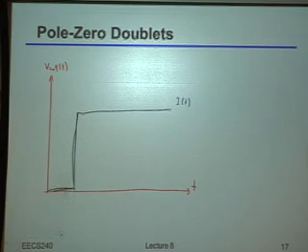Okay, well, if I have just some generic second-order system, then what you'll always get in terms of the output response, at least as long as it's overdamped, is something that looks like the composition of exponentials, where the time constants of each of the exponentials are basically related to the poles in the system. Okay?